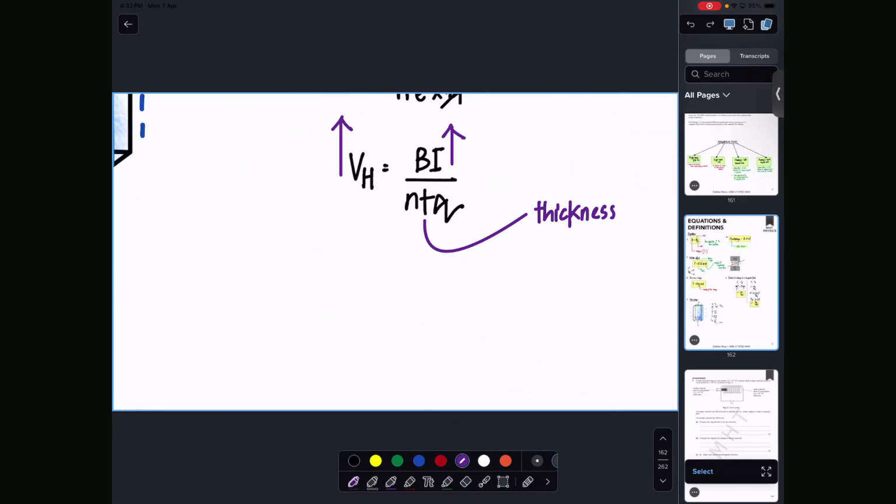I'll explain what I'm trying to look for. There was this one question, and I don't remember where exactly. They were saying that if you heat a semiconductor, it becomes a better conductor, from your AS. Remember that when temperature increases, more charge carriers are released, and that makes it a better conductor. n increases, right? So the question is, if temperature increases and n increases, then the voltage will decrease. Wouldn't it be a bad thing? But there was one question, I don't know if it's Cambridge or edX, but they said it's not an issue. Why is it not an issue?